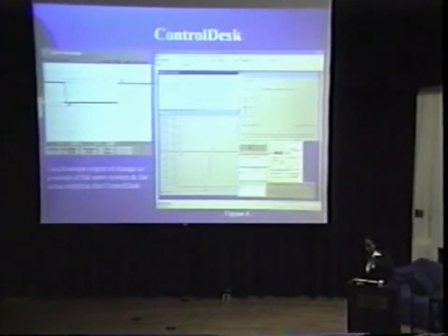After a model is built in Simulink and an experiment is created in the control desk, the variables that can be changed in the system will automatically link to the control desk and appear in a tool window. These variables then can be dragged and observed in the layout, like the one shown in Figure 5. In this example, the position gain could either be changed by numerically inputting the gain desired or using something like a slider bar and just change the gain. This would take effect immediately. You would be able to see it in the scope and in the control desk.